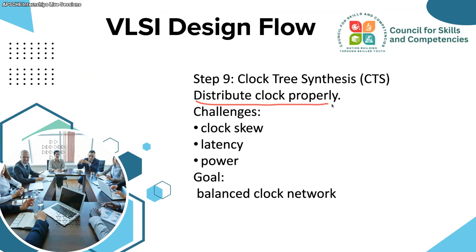That distribution of the clock is done properly by this clock tree synthesis. So the clock skew, how fast it is, what its delay is, and what power it is taking. At the end, we need a balanced clock network. That is the goal of this ninth step.